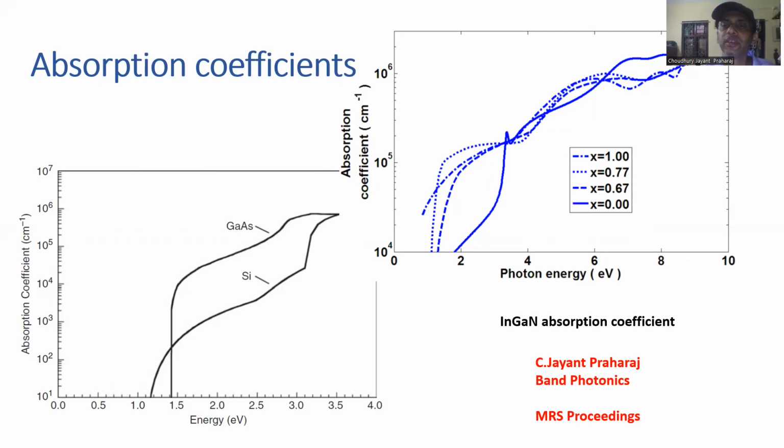And then especially as the effective mass varies, for example, the acceptor binding energy also is different. And for large gallium composition, the effective mass is larger and the acceptor binding energy is larger, and that leads to lower ionization of acceptors, and that leads to lower hole concentrations.